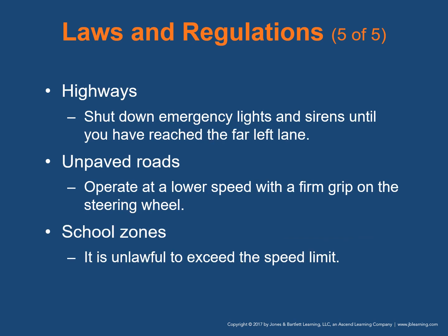On highways, shut down emergency lights and sirens until you've reached the far left lane. On unpaved roadways, take special care. Operate the vehicle at lower speed and maintain a firm grip on the steering wheel. With school zones, it's unlawful for an emergency vehicle to exceed the speed limit in a school zone regardless of the condition of the patient.